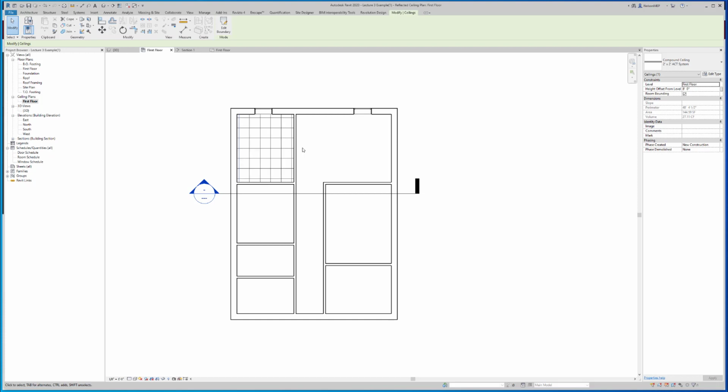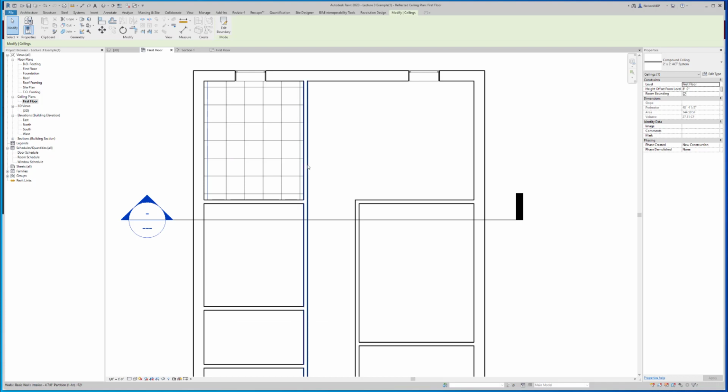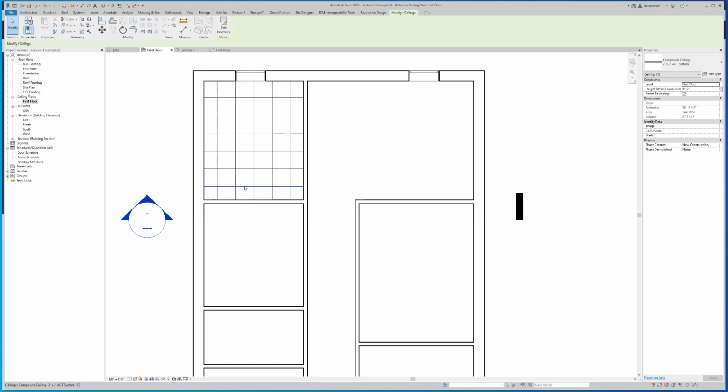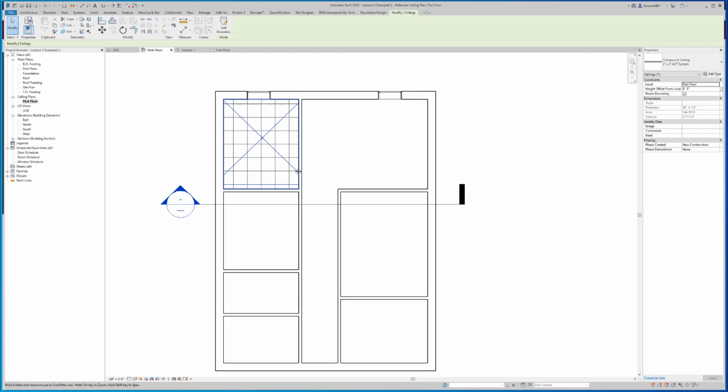One thing you want to avoid in ceilings is this would be kind of a tough design, but tough install. So if you see here, there's just a very thin edge, very difficult to install, a little bit of waste. So you want to try to avoid that. As you're laying out your ceilings, try to keep it balanced as you can, centered, and stay away from those small little slivers here. Okay, that's going to be pretty close depending on how we want to lay that out.